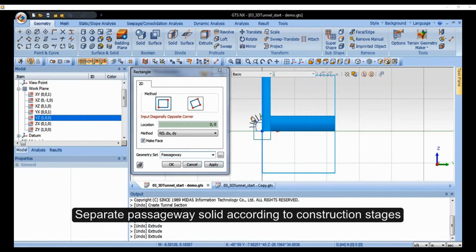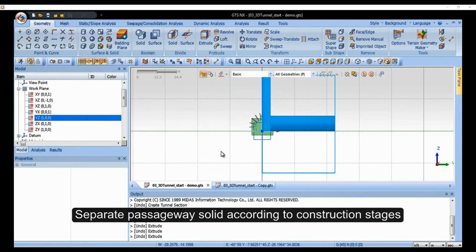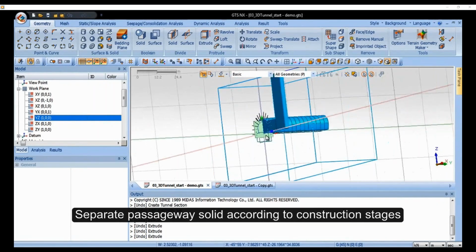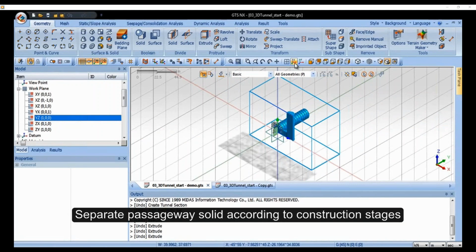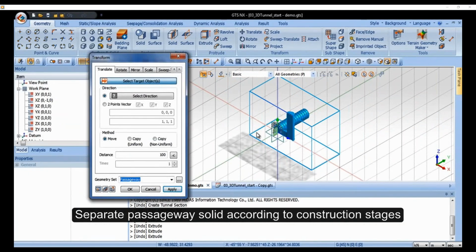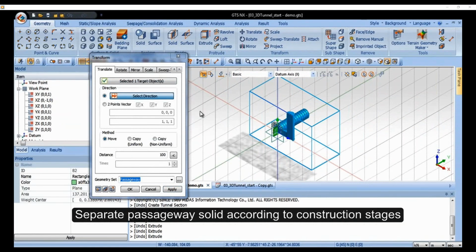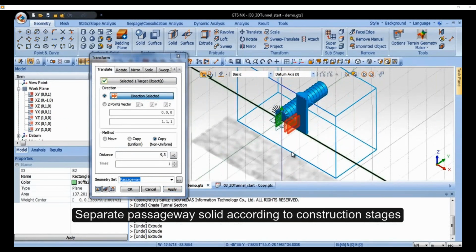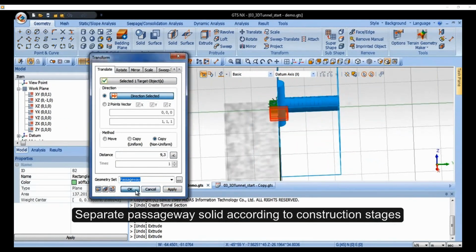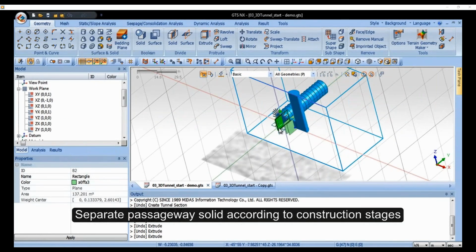I'm going to draw a face just big enough to cover both faces of the complete face of the tunnel. In this case, it's basically just half. And again, we're going to make copies of this plane or surface, this time non-uniform. So I can specify by separating with a comma. I can tell it at 9 meters, and then after that, 3 meters further, so that's why the comma is there, to create these two surfaces. So it doesn't have to be uniform. You have a lot of control in that distribution.